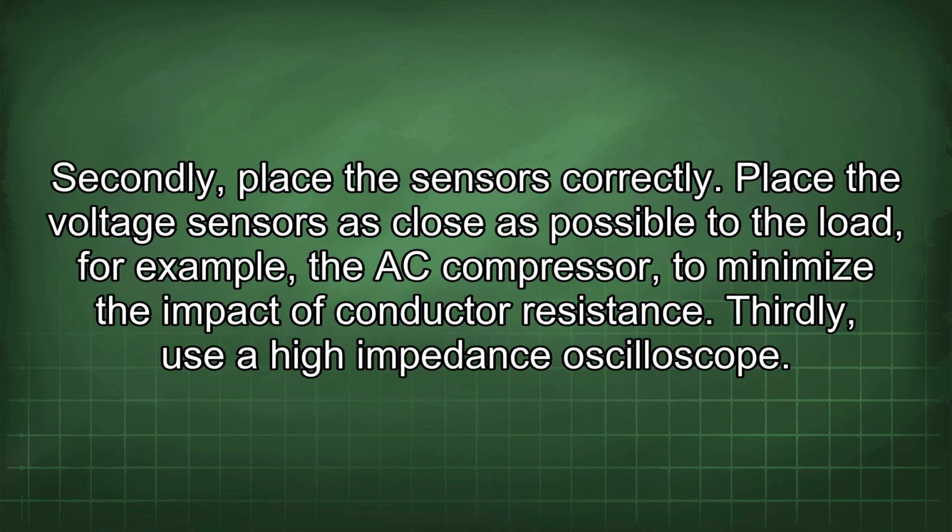Secondly, place the sensors correctly. Place the voltage sensors as close as possible to the load, for example, the AC compressor, to minimize the impact of conductor resistance.